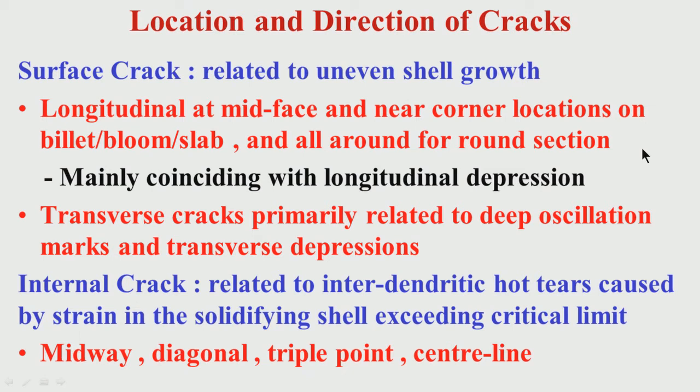So, this low temperature brittle zone will not be there, because the nitrides will be forming along the grain boundaries of the finer grains, which is a quite large area. So, the density of formation of the nitrides will be less, and the brittleness also will be relatively less. So, the reasons for surface crack formation are twofold.